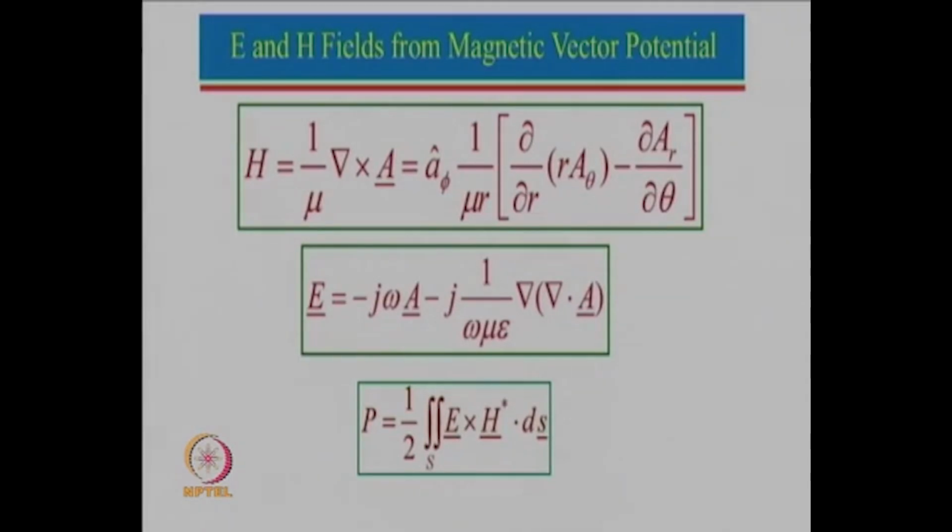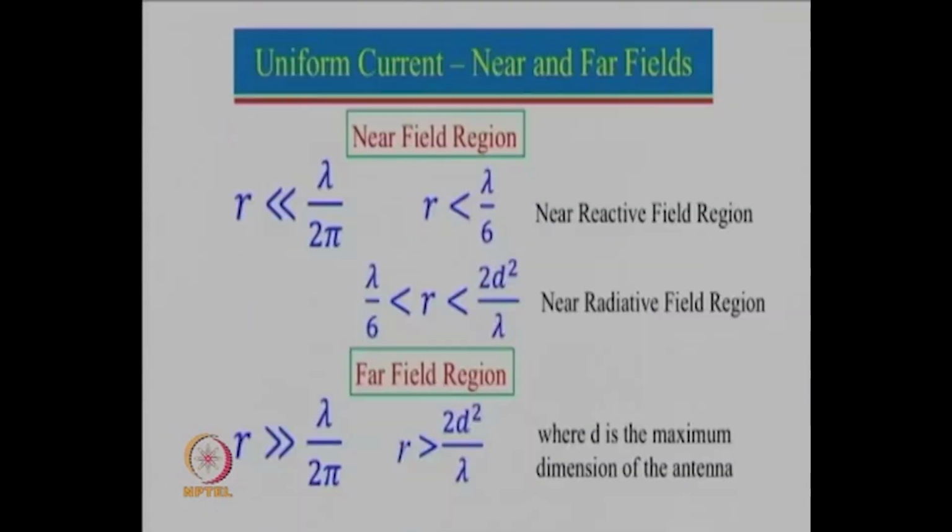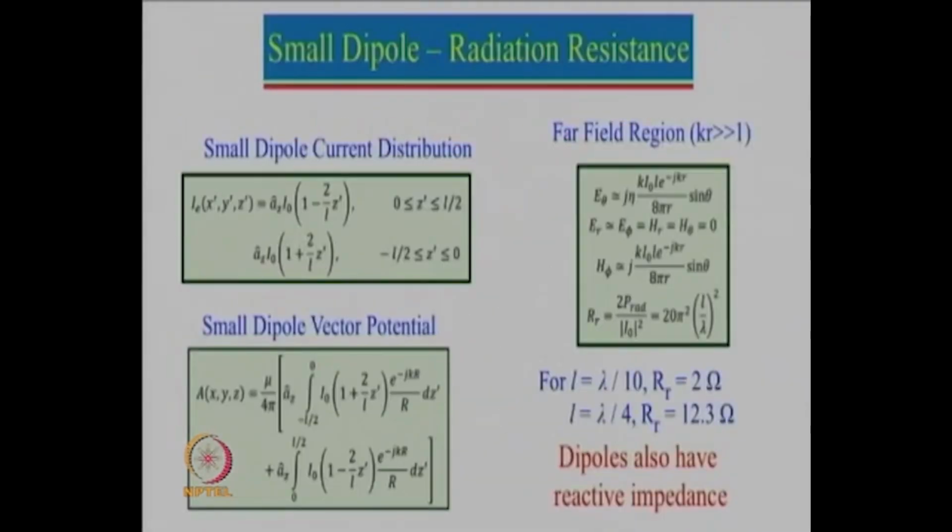Now, what is this RR? I just want to mention here that RR is actually nothing but a radiation resistance. It is not a physical quantity at all. From antenna point of view, power radiated is a fantastic thing. It is radiating in free space, that means the antenna is radiating. But from circuit point of view, the radiated power is actually a power lost.